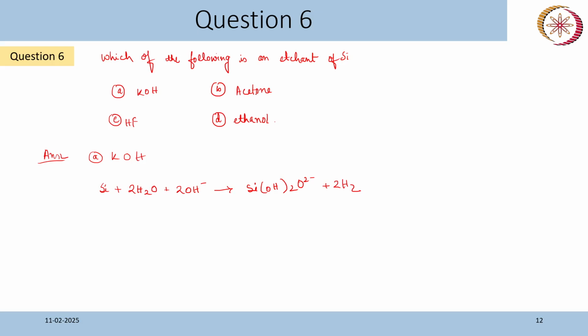Acetone, for what material can acetone be an etchant? You can remove most photoresist with acetone, so this can be an etchant for photoresist. And HF is the etchant for what material, if you know? So this is for SiO2. We normally use buffered HF solution, just to achieve controllability, so that we can control the concentration and the etch rate of our SiO2 etching. Ethanol, I don't know if it is an etchant for some material. You can look if you want.